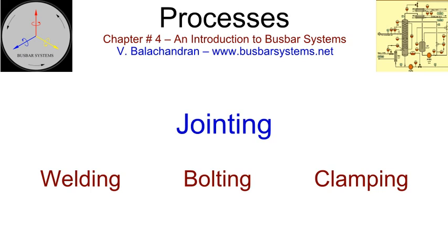Clamps are also used for holding the parallel conductors of the same phase. This is different from the clamps used for current transfer and act as current equalizers. Such clamps are necessary to limit the stresses and deflections between the conductors of the same phase during short-circuit forces. Such clamps are also used on bundled conductors in transmission lines and are referred to as spacers.